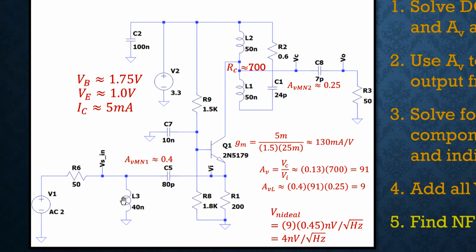First, I'll orient us. This is the source over here on the left, obviously. And this was our matching network. We come into a common base amplifier, so the base is AC grounded with C7. And the output signal comes out on the collector, and then it goes to another matching network, which is kind of merged in with the LC tank circuit.